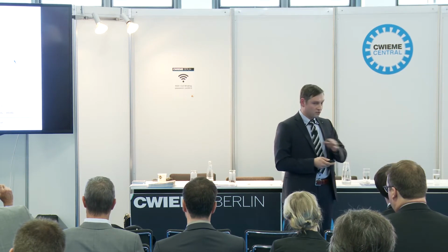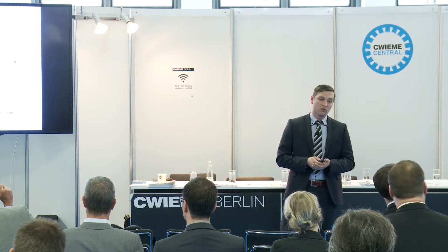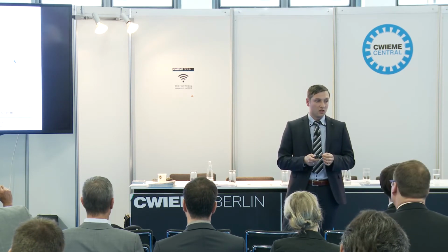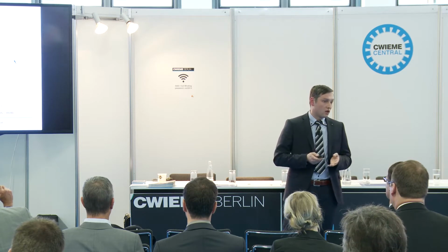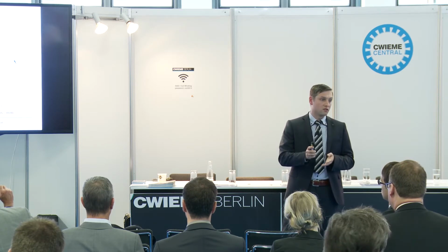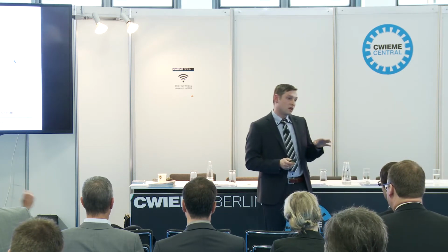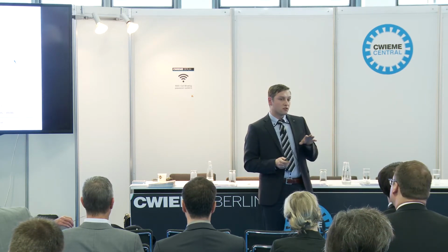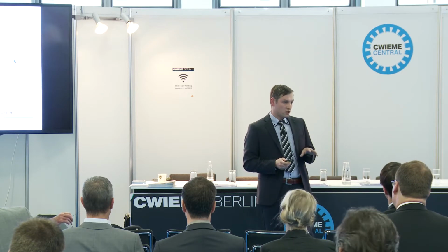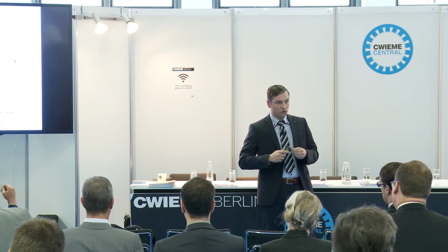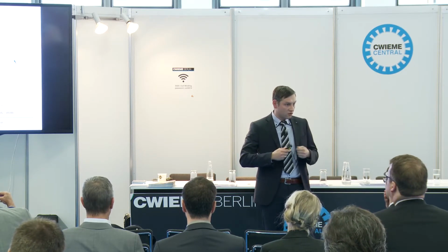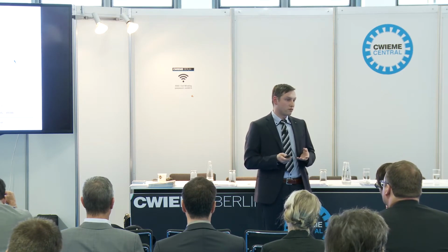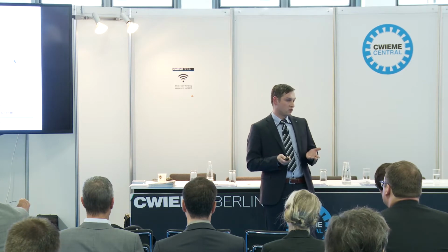The idea of this surface treatment is to modify the residual stress state within the lamination. For example, punching induces tensile stress in the lamination, and if we apply a surface treatment strategy that induces compressive stress, then we can reduce this tensile stress, which results in an improvement of the specific core losses.